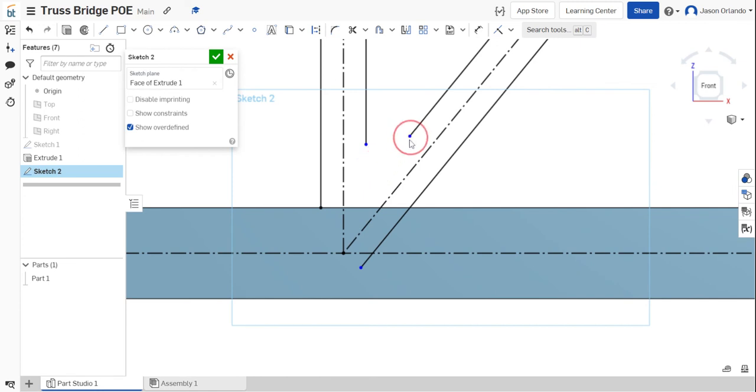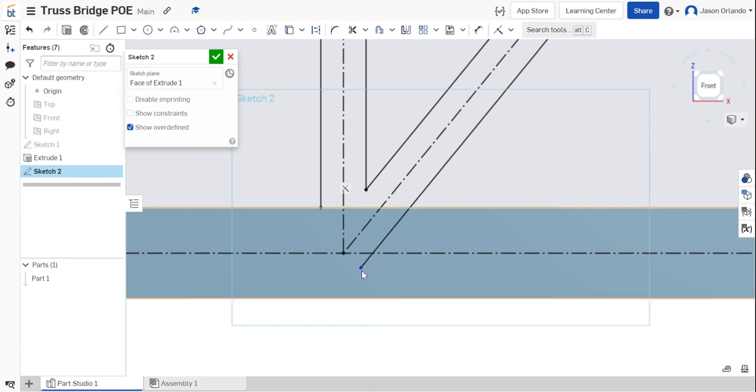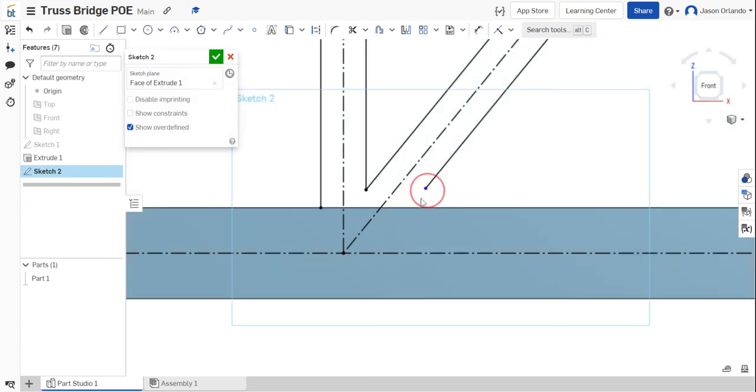All right, so if I'm clicking and dragging and holding it, if I keep my mouse button held down and I hover over that one, it will light up, and it knows that I'm actually moving this one, and that will create the coincident constraint, and they'll both go to the length they need to be so they intersect and connect at the endpoints. So when I let go of my mouse button is when it did that. Okay, so I'm kind of clicking, dragging, hovering over where I want it to connect, and letting go.